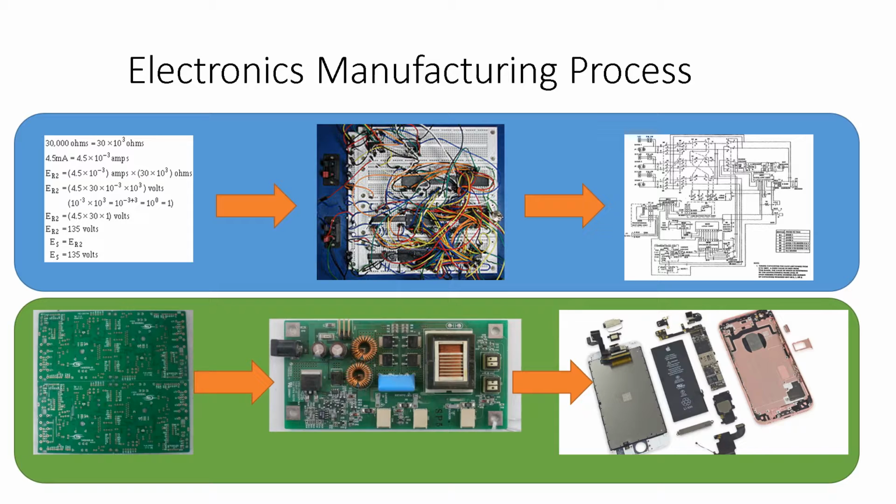And there's a whole bunch of things you have to know about the electrical circuit and the schematic before you do that. You have to know which parts get hot, where they're located, so you don't have parts that burn out. You have to make sure that parts that need electromagnetic interference shielding aren't near each other, because you'll have interference between them. You need to make sure that you can design for manufacturability, that the circuit board is essentially a standard kind of size and follows standard hole dimensions. You need to know where to put thermal vias to remove some thermal heat. So without an understanding of how that circuit works, you're not going to be able to do your job of taking that circuit and turning it into something real. So that's where your first step starts.